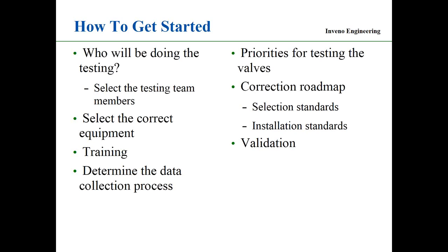The thing is the priorities for testing the valves. If I have to go out and test 20 bypass valves, and I come back and 10 of them are leaking, what degree of leakage? So I set priorities. The ones with the highest ultrasonic level or flow are the ones I'm going to do first. The ones with very low ultrasonic levels are a lower priority. So I set priorities depending on my test results.